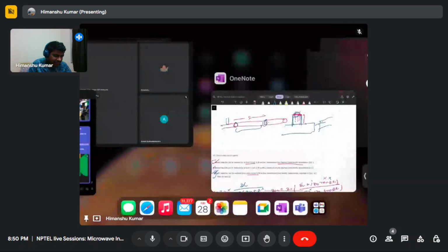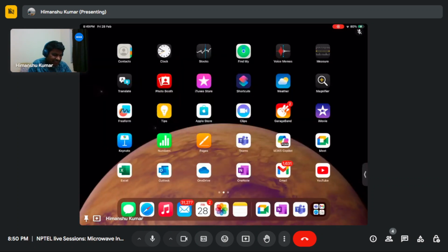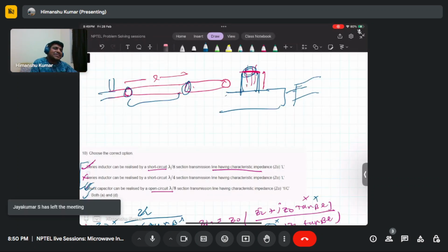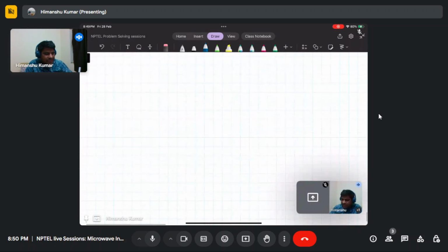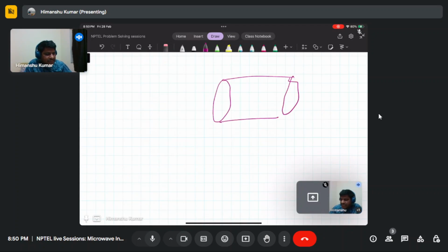And I use it in my lab. I use this triple stub tuner. I work with this spin cavity system. I have a resonator, a microwave cavity resonator. To excite that resonator, I use a coupling loop. Because that is a shorted coupling loop, its input impedance will not be matched.